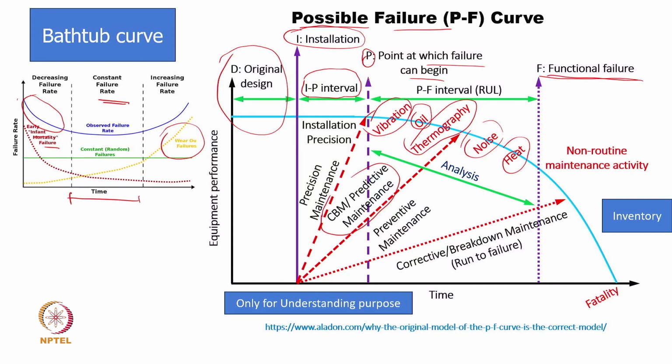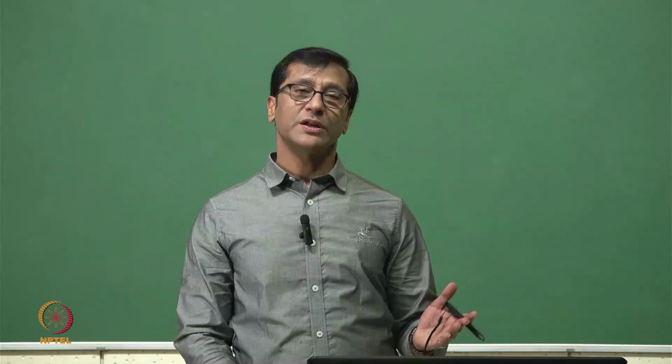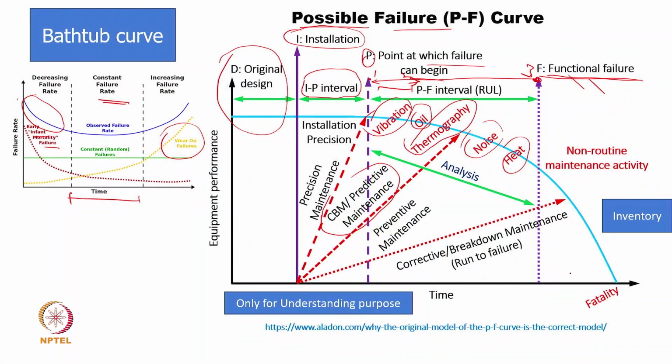So if the failure starts from here to here, whatever the overall life, if this has been passed in this 1, 2 and 3, say if the 1 and 2 is over, so we say remaining life is 2, 3, or if the life has reached here, we say the remaining useful life is 0, and after that the component should be replaced. However, if we have condition based monitoring, then we may not really require this. We may go ahead with more correction, and then we keep extending this line to this side or maybe this side. That's what we have earlier mentioned.